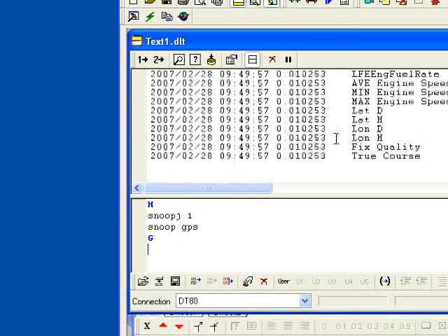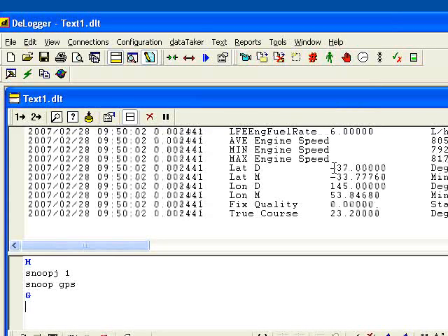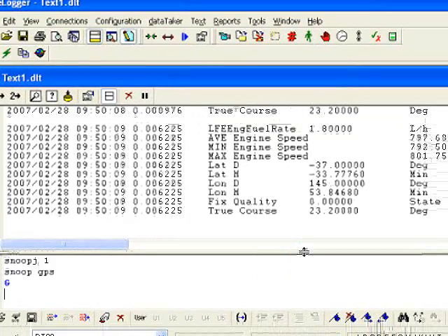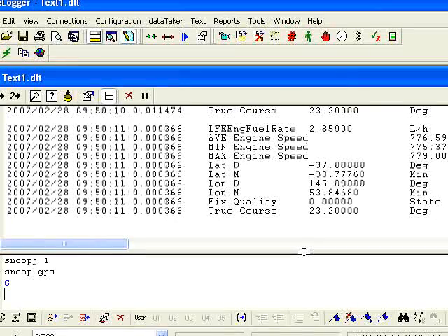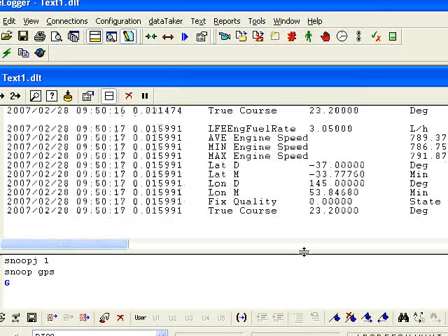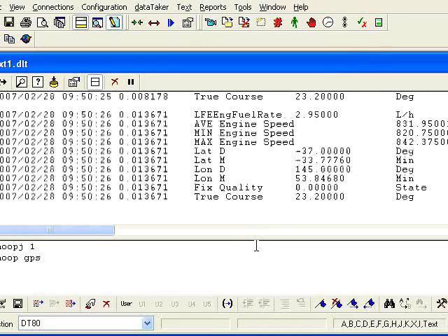We can use the CANgate to very easily collect information from two independent CAN bus systems or a GPS if appropriate. This information can then easily be integrated with standard analog measurements that the logger makes. All of these measurements can then be either stored, sent via FTP, or collected by a Modbus-based system. The CANgate integrates CAN bus into the simplicity of the dataTaker system. The DT80 and the CANgate make a very powerful combination.